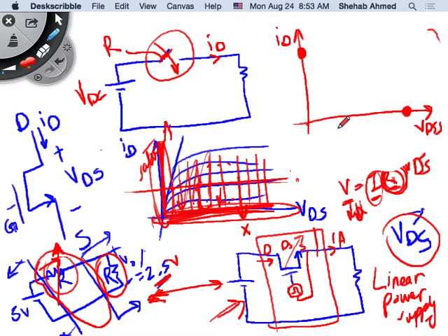Does everybody get the idea of, okay, this was the original characteristics, and now really a MOSFET, if you operate it only in saturation and cutoff, looks like this. It looks like the ideal device, ideal switch. So forget about 325. We're operating an ideal switch, except we're adding a little bit of a twist. Instead of just an ideal switch, we're adding a switch with a resistance through it. That's all we're doing in 438.